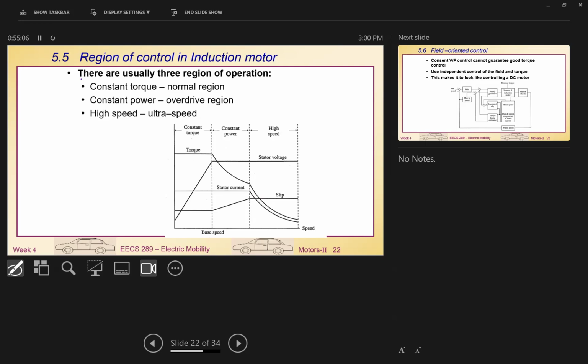However, one thing will happen: the motor power cannot increase further with higher speed. What do you need to decrease to compensate? Power is torque times speed. The power of the motor is already fixed; you cannot overdrive the motor with higher power. The maximum power is fixed. So when you want to increase the frequency or rotation speed, the torque must decrease. That's why you see the torque decreasing in such a way.